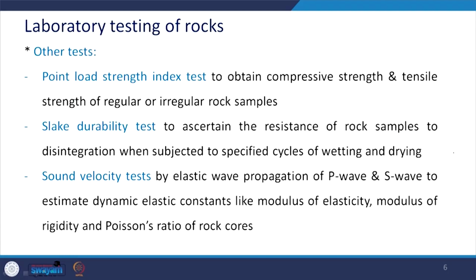Some of the other tests which are there apart from these include the point load strength index test. So, apart from the unconfined compression tests, this test also gives me the idea about the compressive strength and also the tensile strength of regular or irregular rock samples.